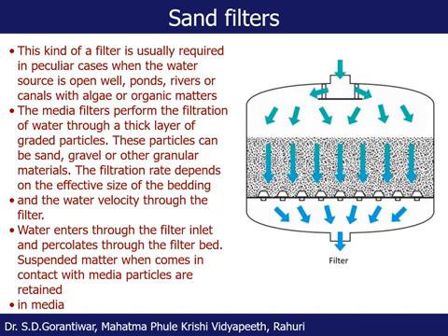These are the small filters actually. So what happens when water comes inside through the inlet, this water with debris and impurities will pass through this sand bed. While water with impurities is being passed through the sand bed, the impurities are retained in the sand bed or above the sand bed, and impurity free water will be screened and will pass into the outlet actually. In this way this filtration mechanism happens.